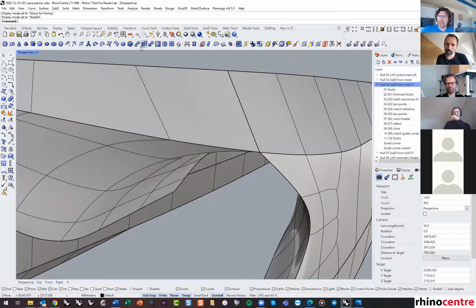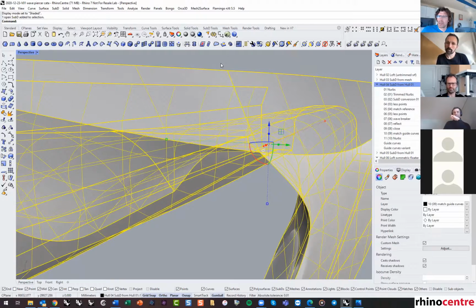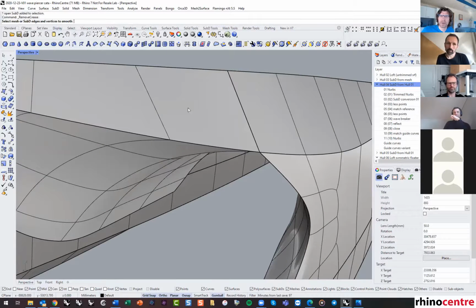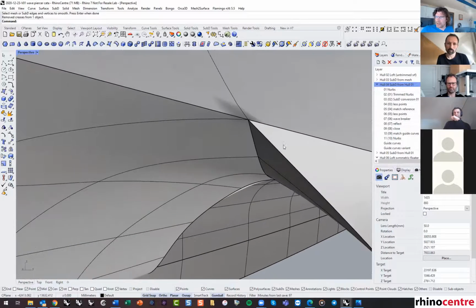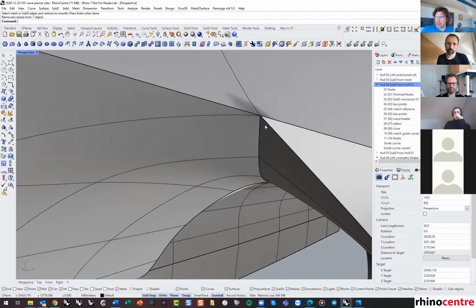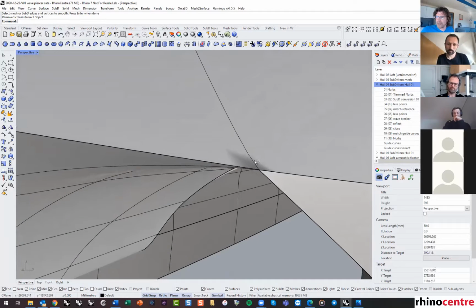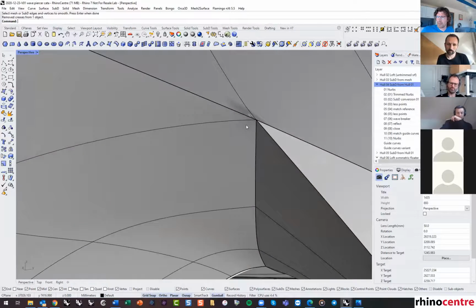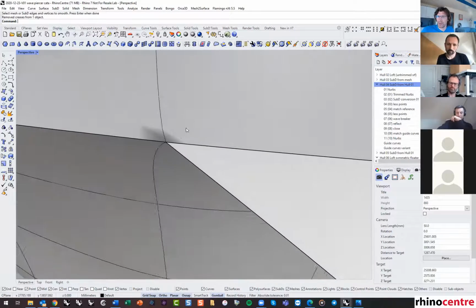If I remove it, then you see another limitation of where we are. Let me see. This was something that was also a problem in T-splines, because you could not always remove crease. So here you see a limitation. If you have hard creases joining in one point and there is one soft crease, then you have this problem in the continuity.